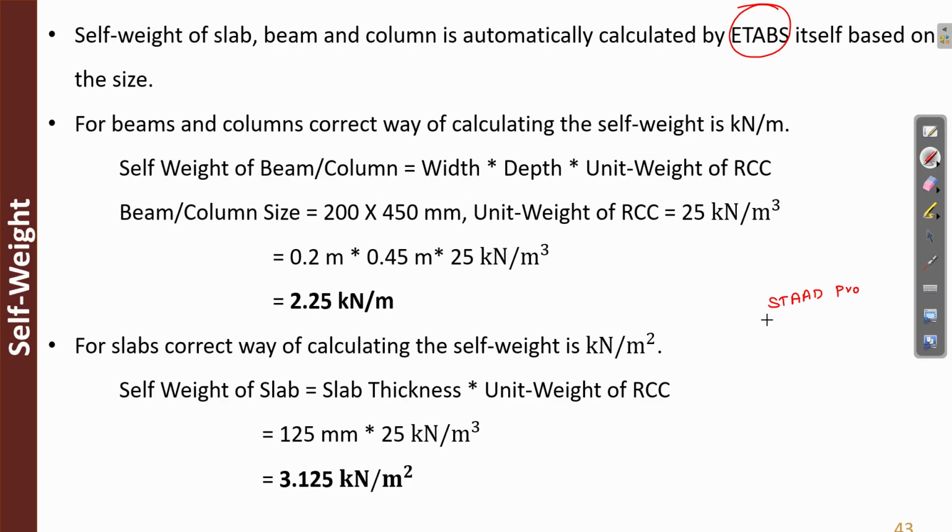In STAAD Pro, you need to provide a command. If the element is not a part of the STAAD model, self weight will not be calculated. Similarly, in ETABS also, if the element is not a part of the ETABS model, self weight will not be calculated.